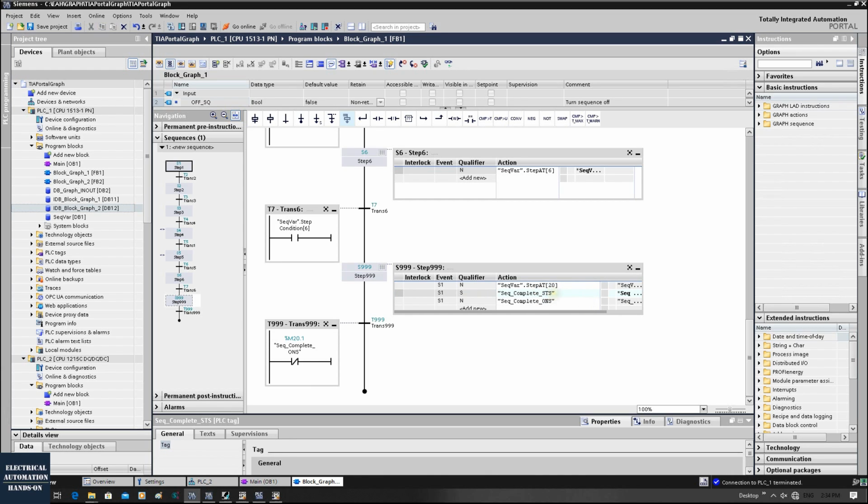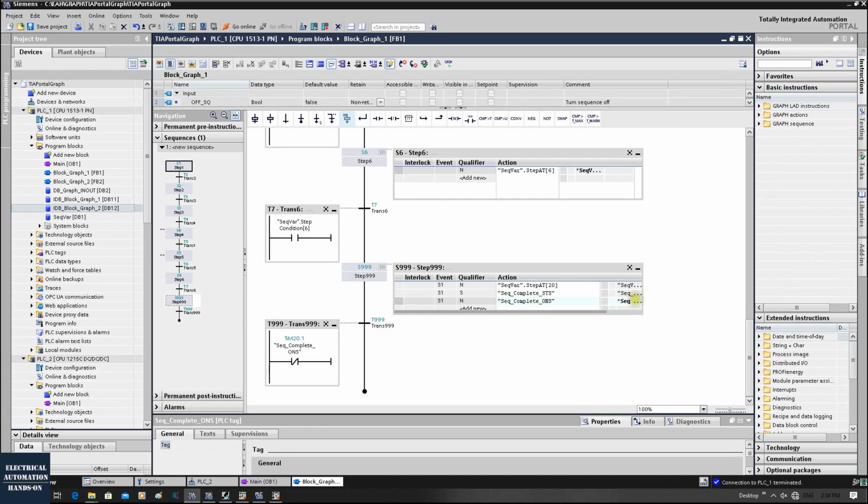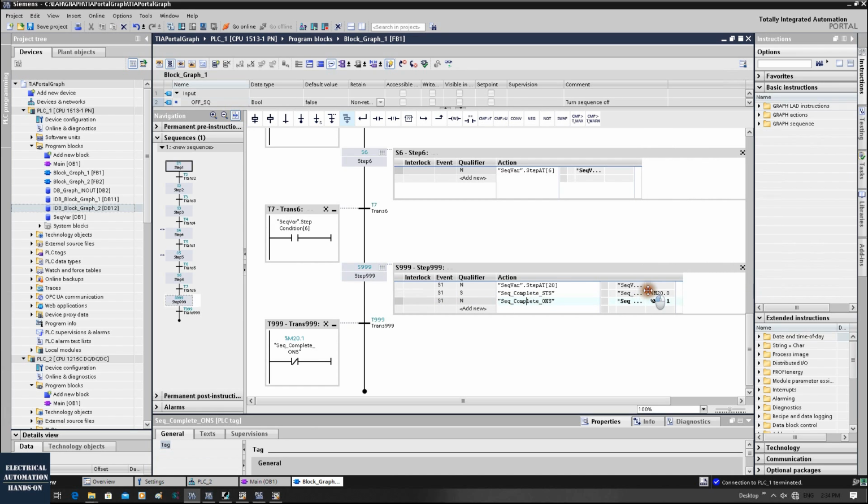I usually call this STS, status. So we set this status. And in the meantime, this is also my personal flavor, I will still use the S1 rising edge, and use this N command. N means coil, right? And it controls this bool. This bool can come from a DB or M address, and it will be a rising edge, just one cycle on. This can be used to trigger anything. For example, this bool can be used to set any other flag or trigger another sequence start, or some other purpose. So basically I have one flag signal and one trigger command signal representing this sequence complete.